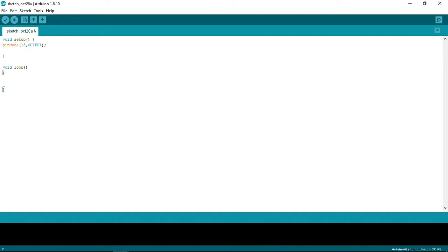what I'm going to do is blink. So I will write digitalWrite pin number 13 HIGH. This will make the light at pin number 13 high. Then I can put a delay.